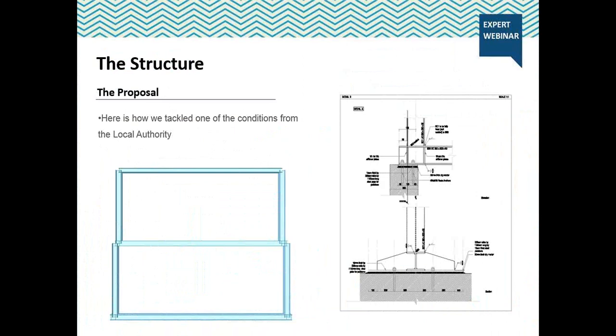In accordance with the conditions set by the local authority, we had to set back the 5th floor facade by 200 mm and the 6th floor by 510 mm from the existing brickwork. To achieve the setback above and still keep the load central over the perimeter wall, the ends of the main beams are cantilevered. The effect of this creates a staggered frame as shown. Also shown in the detail is the bearing pad we used to connect the frame to the perimeter wall.